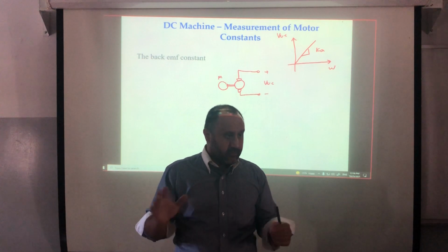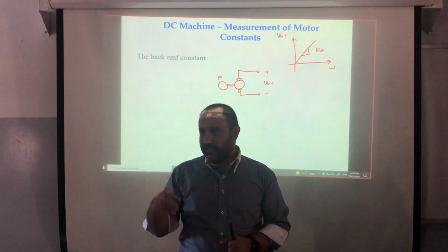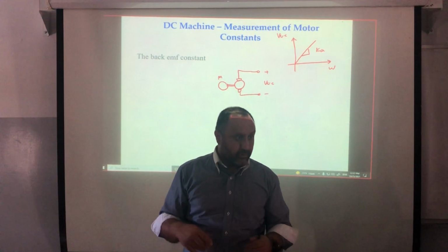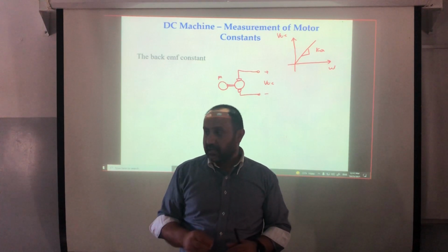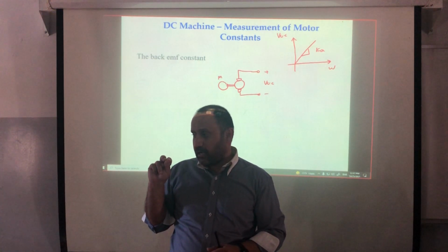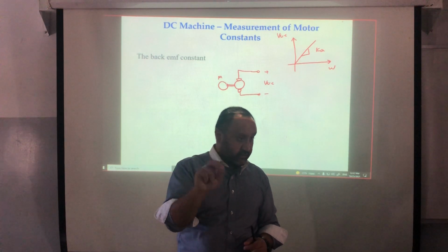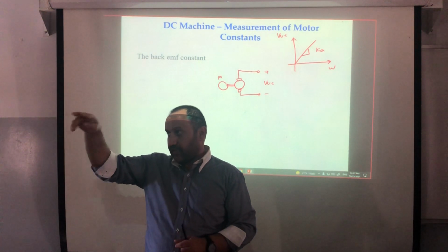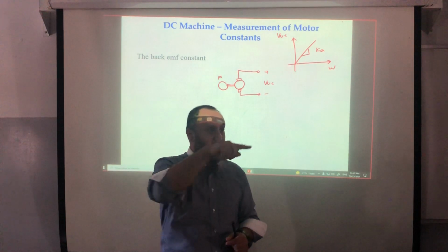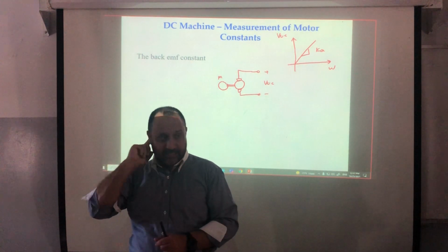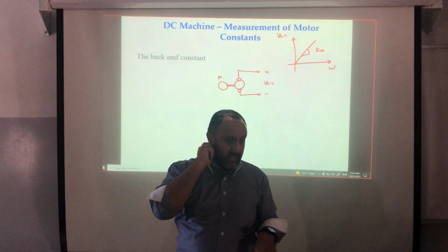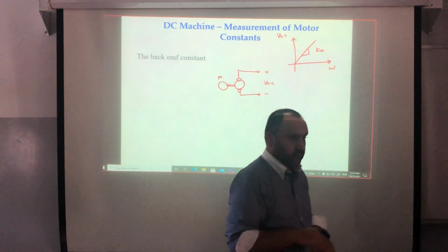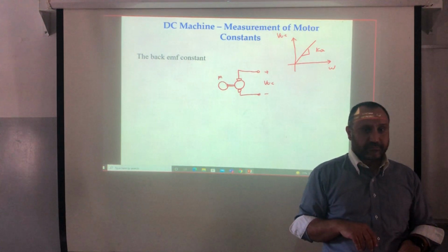The load torque T_L is 0. So simply in the end of the day, you will get a free run machine, correct? A no load machine, no load test. So if I'm giving now a current reference step, I will get a step response in the speed, which has omega steady state, and I can calculate the final value, or the steady state speed, and the time constant. And from there I can calculate the B and the J.